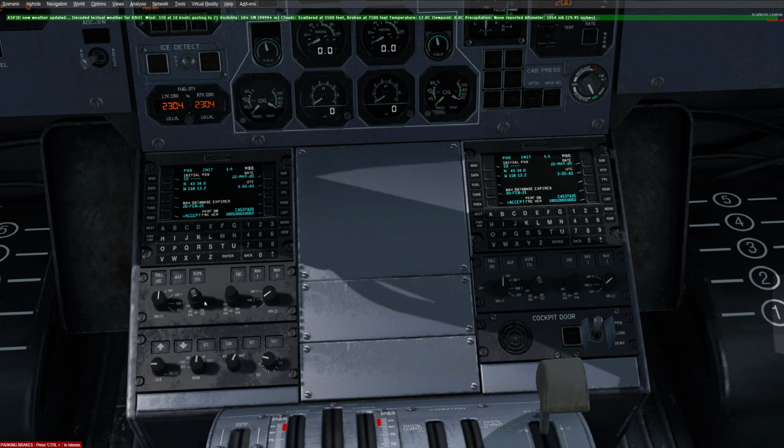This little rectangle here is the EFIS control panel. It's got a lot of good features. Full arc, map, ground speed versus time to go, bearing knob 1, bearing knob 2. Bearing knob 1 is good for a blue pointing arrow for these features and a green pointing arrow for those features, just to show the color differences. And then these are for dimming.